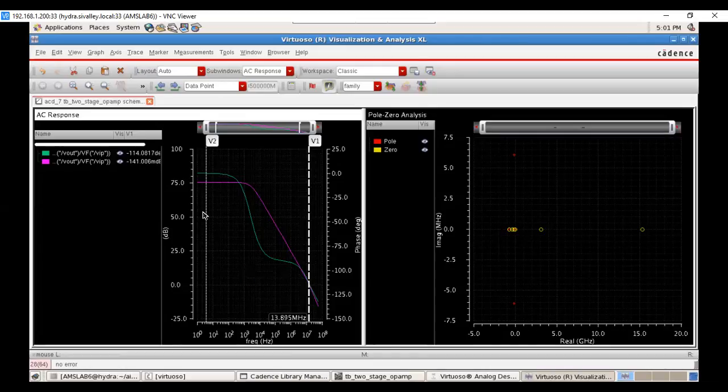And if we take the gain, we have designed it for 2000 magnitude. So I'm getting 75.5 dB, which is nothing but 5600 and above. So that's also good. This particular Opamp is, as far as typical use is concerned, a very good Opamp, and we can use it for even higher frequencies like 10 megahertz, 12 megahertz, and it has very less error as well. Since the gain is higher, you will get very less error when you compare with any reference signal.